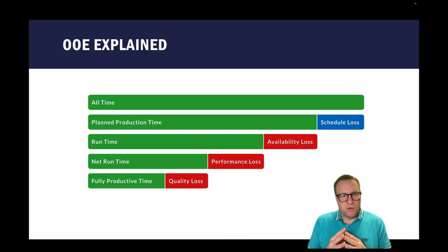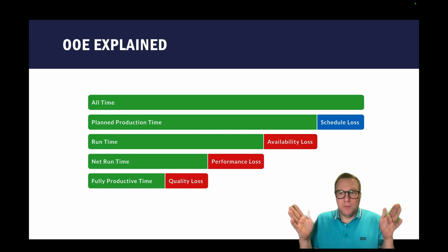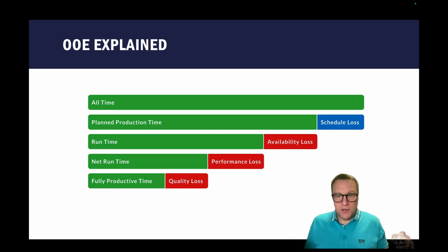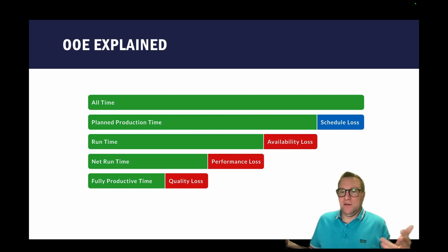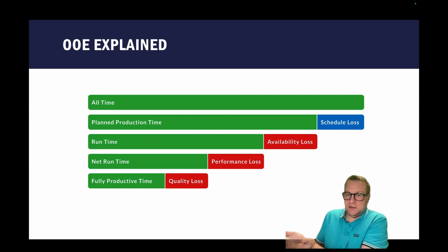And if you think about the overall equipment efficiency, it's about the full time an equipment is really producing or not producing. The first layer, we have seen it already, is all about the scheduling. If a machine is not scheduled for production, then of course it's just standing around and not producing something, and then you have this kind of schedule loss.